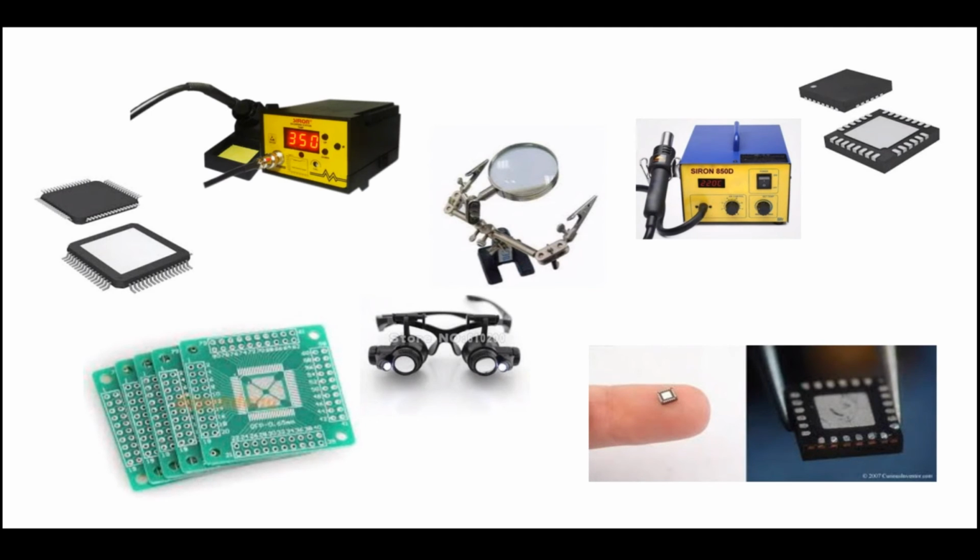So here you might have to use a reflow process, where you apply paste and heat the whole area so that it melts and gets soldered. I got some prototype boards like this from eBay.com, and the way I started was practicing soldering those kinds of chips.